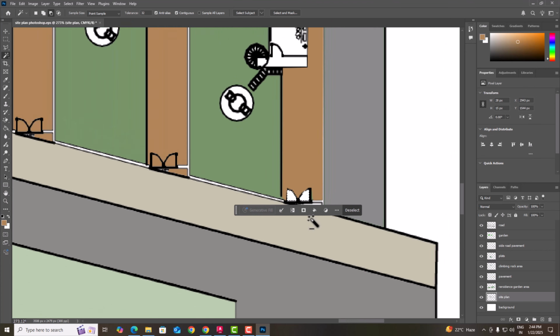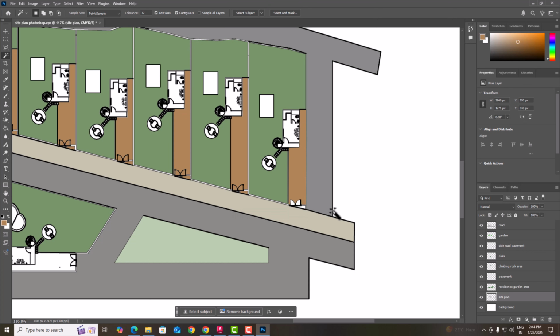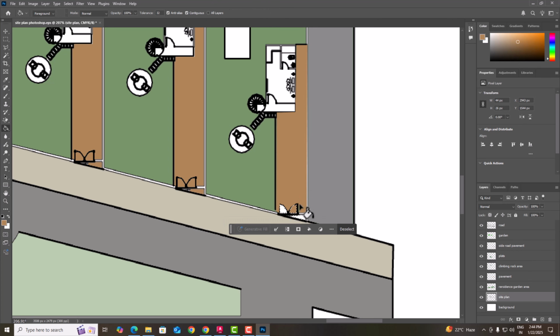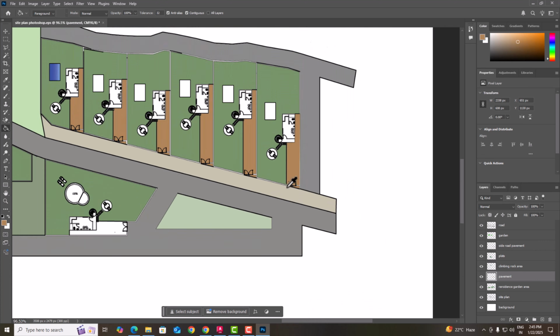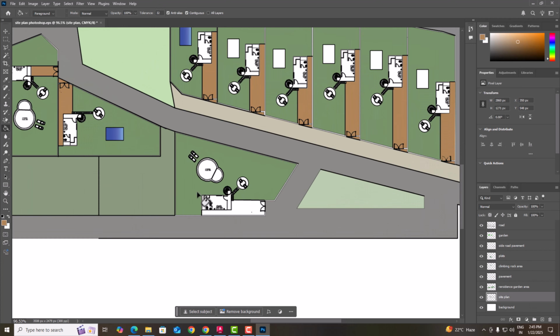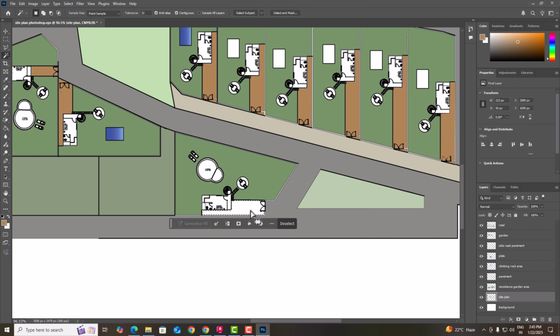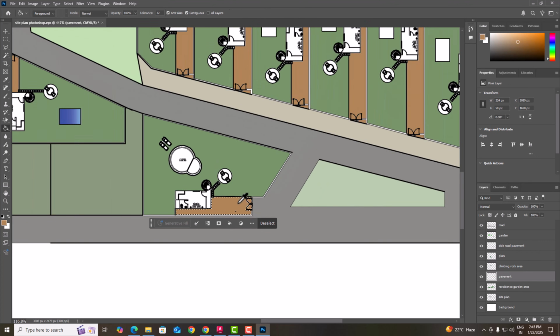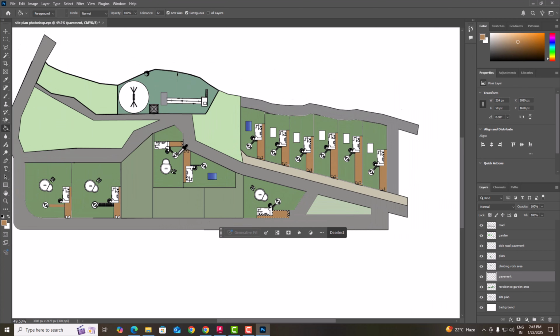And now, so press G command here. So press Ctrl Z, then select pavement and then apply paint bucket tool, Ctrl D to come out of this. So now we have applied pavement and one is left here. So I'm going to select site plan, magic wand tool, and we'll repeat here also. And then I will select pavement and then G command. So now this is applied. So this all is completed here.